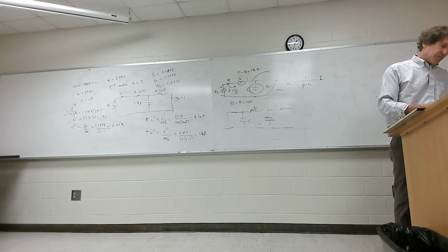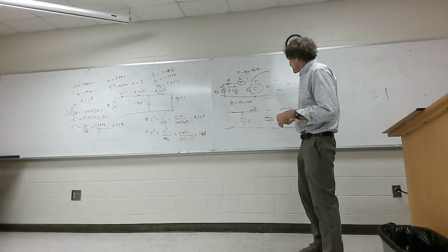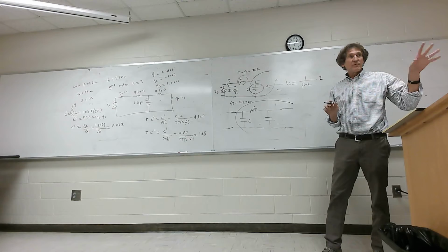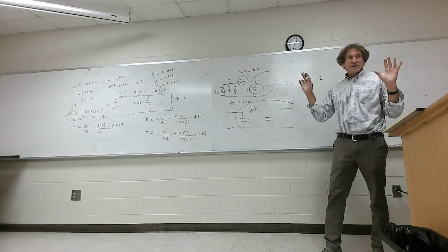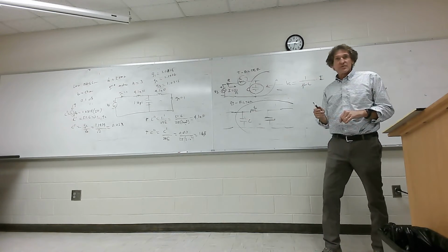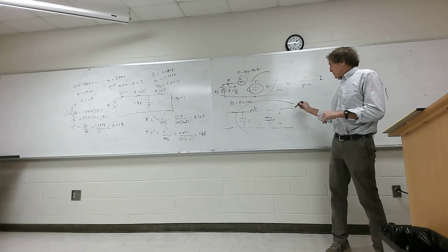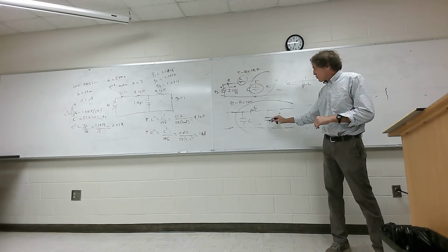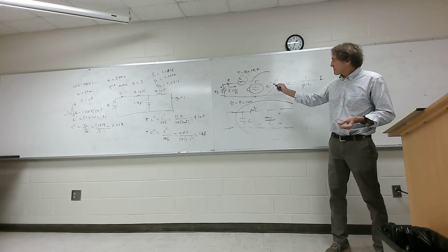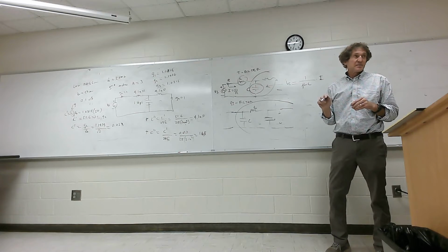I don't even see where he has it here, but normally speaking, in TV power supplies and all this, if you look at anything that takes a full wave rectifier signal and turns it into DC, basically, they'll use a pi filter. The real reason is the capacitor here is going right to the load, and that one more or less holds the charge, so there's not much variability. This kind of filter with that inductor there is not as good at getting rid of ripple at DC. This one's always preferred.